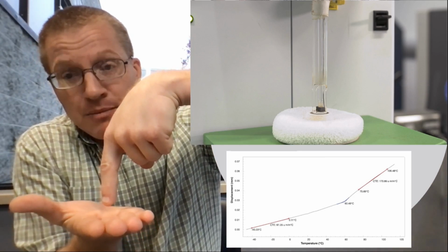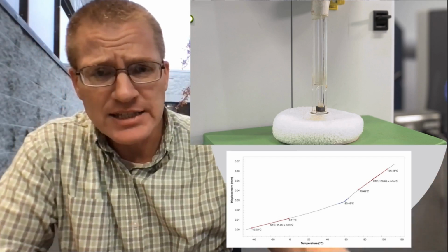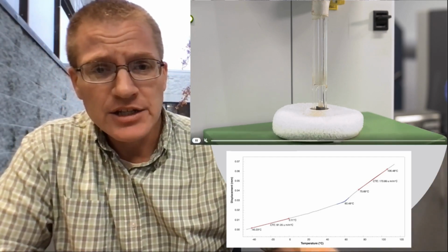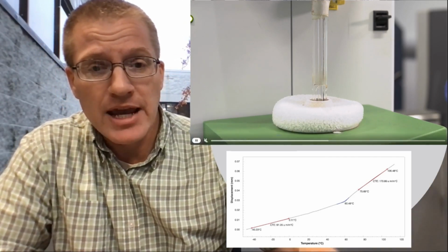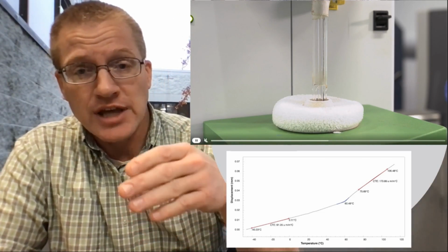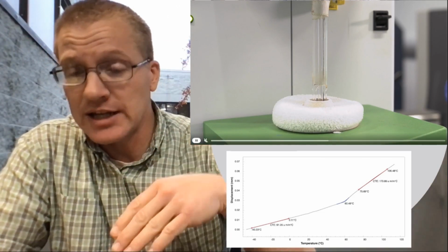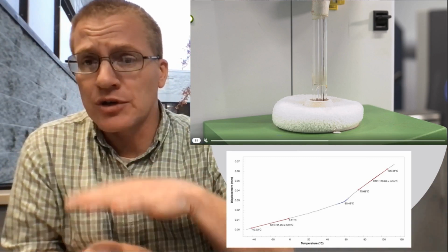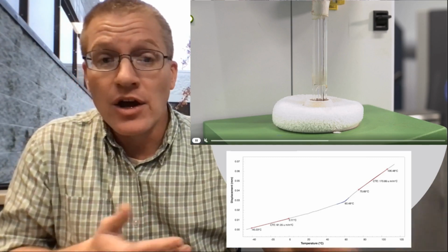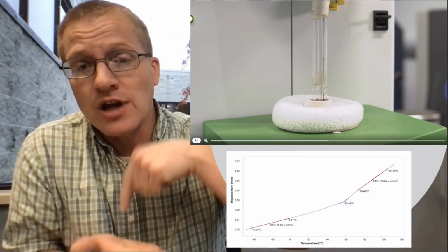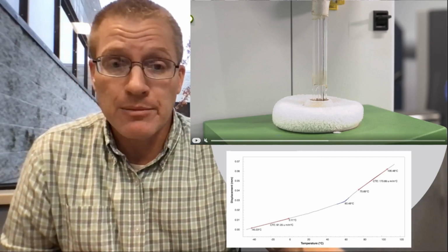And what it's doing is measuring the height. As that goes down into the actual thermal chamber of the TMA, you can see there's frost around the outside of it. So we start off very cold. We get it down in there, we get the temperature equilibrated, and then the instrument measures the height of that sample over a temperature range.